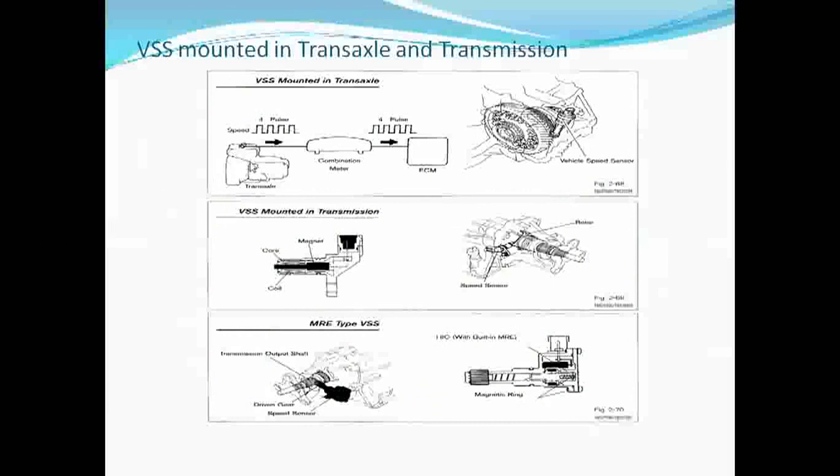Here, the pulse will be generated by the sensor, and that will send a signal to a bus interface system that is connected in combination with a combination meter, and that will give the feedback signal to the ECM. And this ECM will be directly connected with respect to the controller, and the controller will take the necessary action either to decrease the speed or to increase the speed, nothing but the acceleration process.